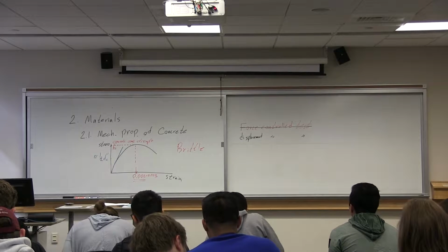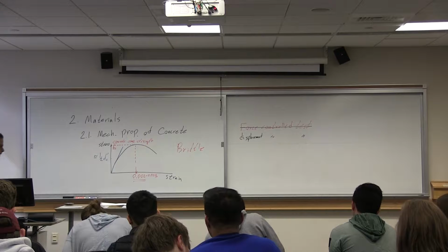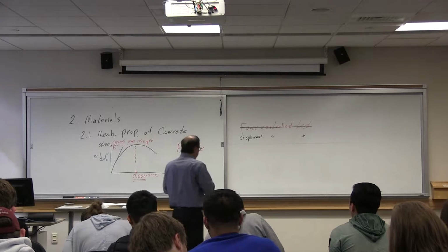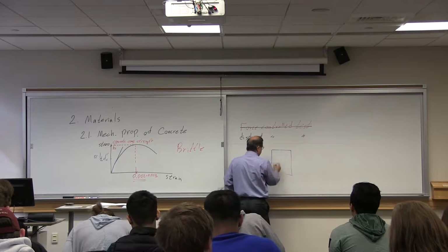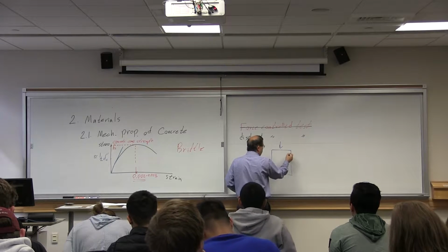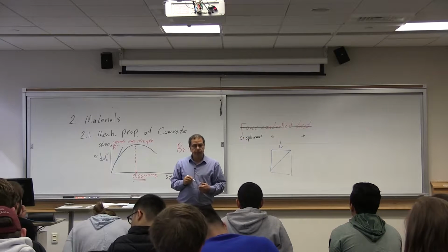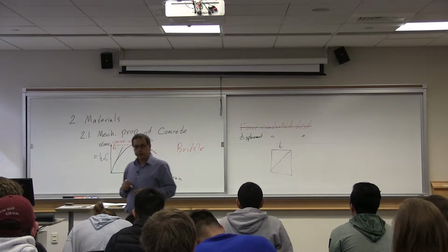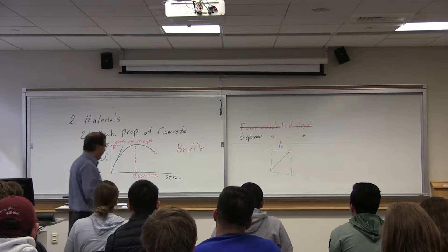When would the specimen fail? When you have a plane of weakness, and then the failure occurs along that line. If you think about a specimen like this, and you apply compression, one mode of failure is that a crack like this would form. And then the sliding happens and the specimen would fail.